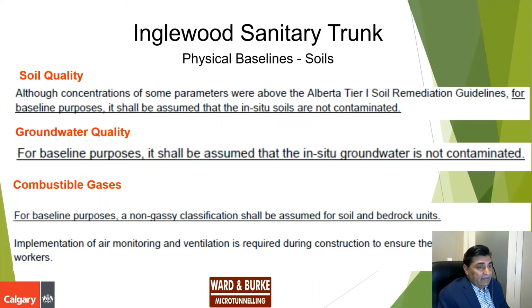Soil quality. So we have to provide a baseline if the soils are contaminated or not contaminated, because contaminated soils have different disposal requirements. Similarly, groundwater, whether it is contaminated or not, has different disposal requirements. So we said soils are not contaminated and groundwater is not contaminated. So during construction, if it is contaminated, then who will bear the cost? City of Calgary will bear the cost. Combustible gases, we said the soils are non-gassy, which means there are no gases in the soil and bedrock.